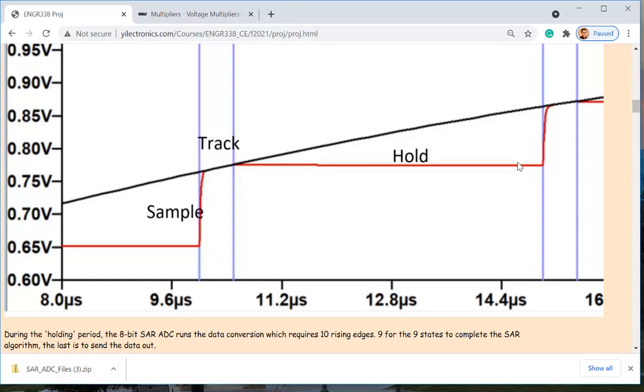So 50% duty cycle is going to work, but it's bad. And I think this one can be narrower, even narrower, actually. And see, it tracked the input for a while, right? For like how long? Like 1 microsecond, right? Which is totally unnecessary. I just need to boom, sample, done. I just want to sample it really quick.